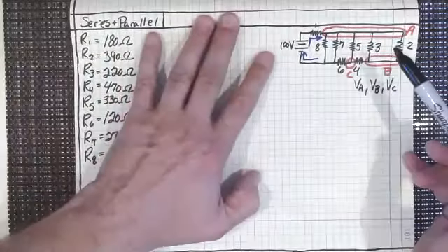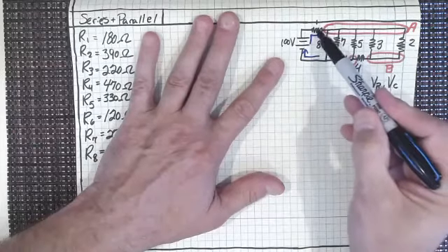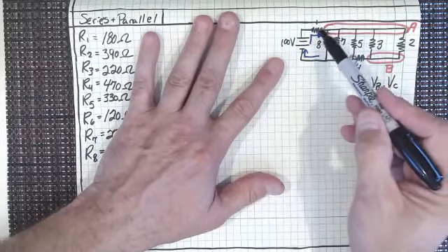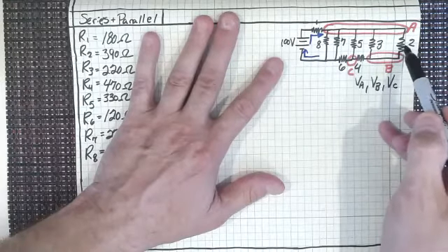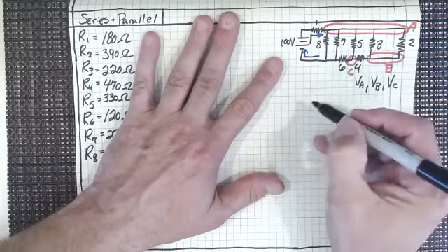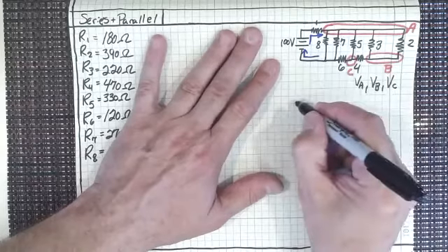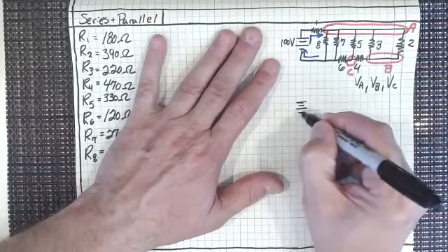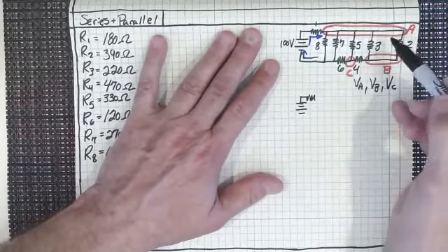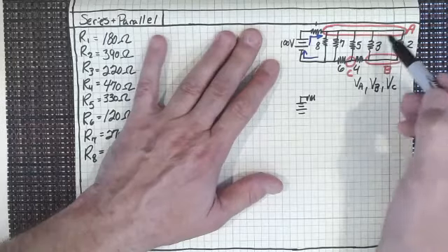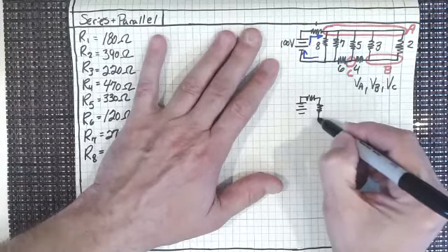We now have them in this, and we can still simplify this further, can't we? Because I think you can see some things that are in parallel and some things that are in a series, right? So if we look down here, we see that these 3 and 2 are in parallel. So the first thing that I want to do is to redraw the circuit, and I'm going to put the 100 volt power supply in there too. But let's redraw the circuit, and let's get rid of a couple things here. Now if we do put those two together, we'll come up with a common one. Maybe I don't want to get ahead of myself. So let's just leave it like it is for right now, and we'll do it step by step.